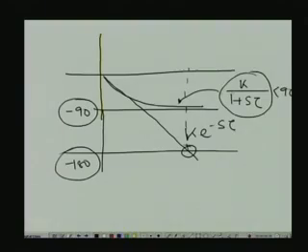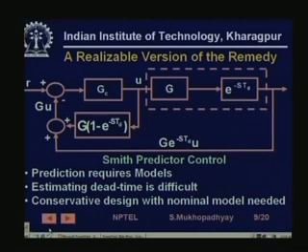But the question is, what is the gain at that point? So to ensure stability, you have to keep the gain low at that point. That's why you have a limit on the gain. While in this case, you don't have any limit on the gain. So you see that time constants and time delays are slightly different, and time delays are potentially more risky, but distinguishing them from time constant may not always be so simple.